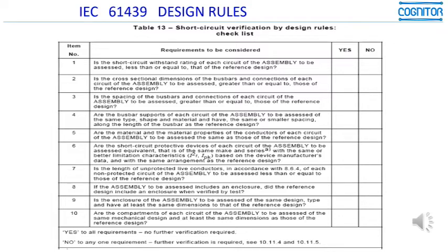concepts involved. Suppose that you test the one equipment and you ask for the one which was not tested: is the short circuit withstand rating of each circuit of the assembly to be assessed less than or equal to that of the reference design? That is, is the short circuit current lower or equal to the one which was tested? Then if your answer is yes, you are a candidate to follow all the rules.